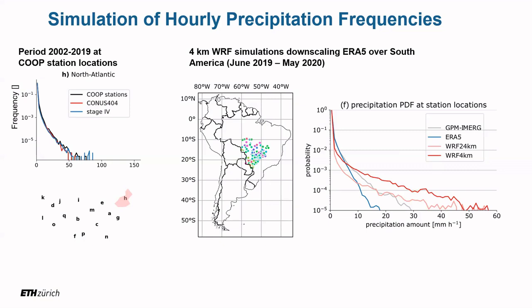And just looking at that, you would conclude WRF is really off its rocker. Like, this is way too heavy rainfall. I see this a lot in published literature, and many people make these claims, like these kilometer-scale models are really overdoing extreme rainfall. I think that is true, but not to the extent that we think it is if we compare it to satellite data sets. Because if you now add the stations into this plot, you can clearly see which of these data sets is closest to the observations.